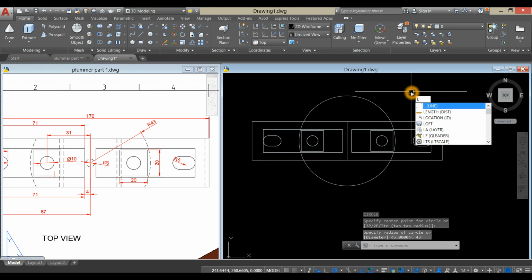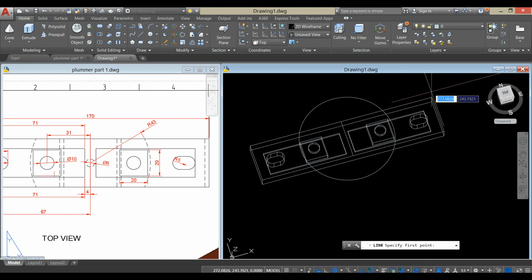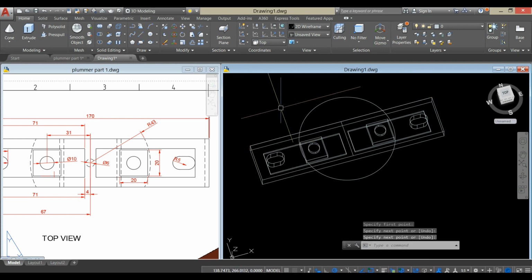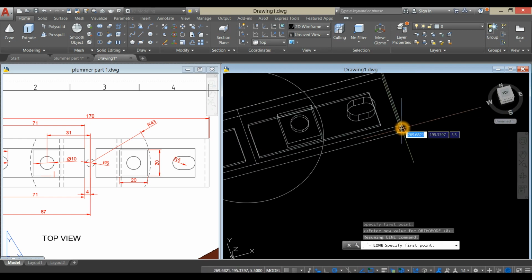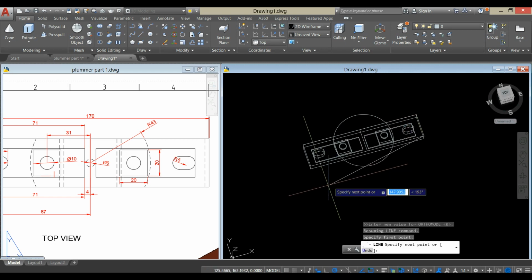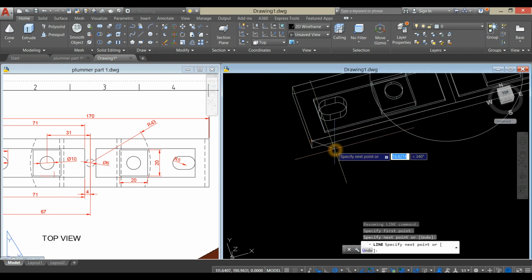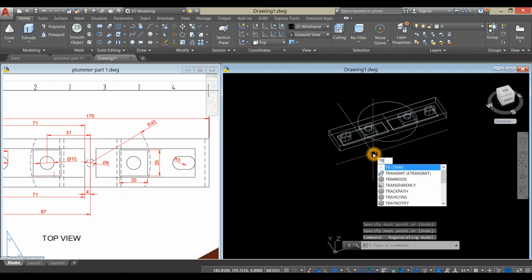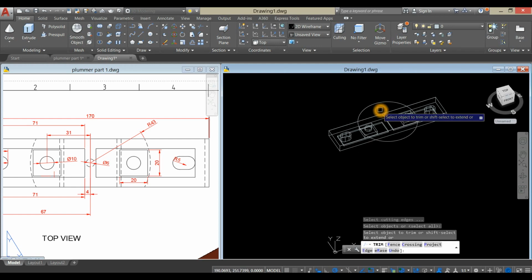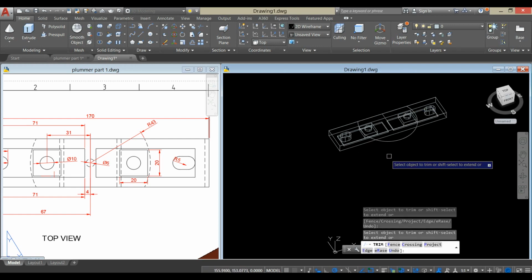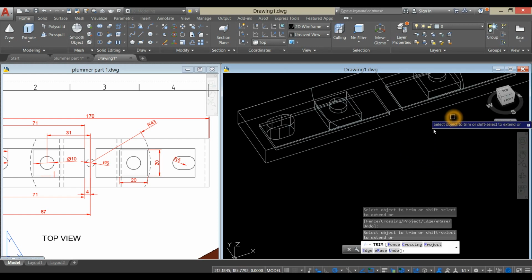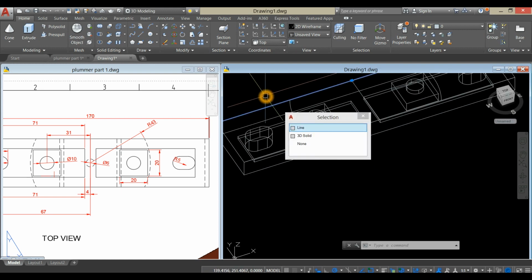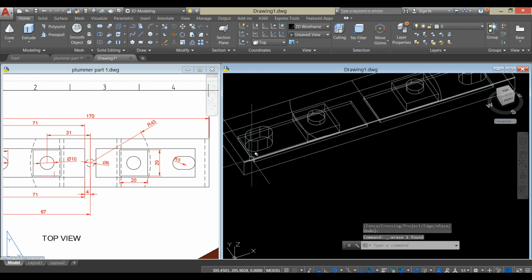I'm going to draw a line as a boundary. So from this endpoint to this endpoint, repeat line from endpoint up to this endpoint. I'm going to trim, so TR for trim command, enter twice. Remove this one, remove this one, remove that. Now we have 2 arcs left. Remove the line. So delete this line.